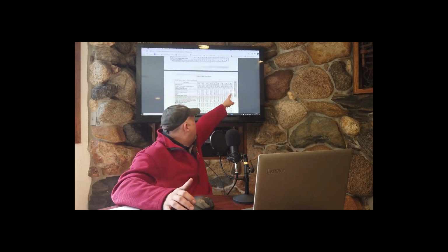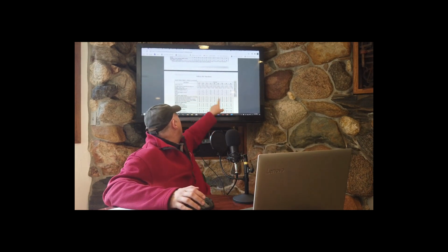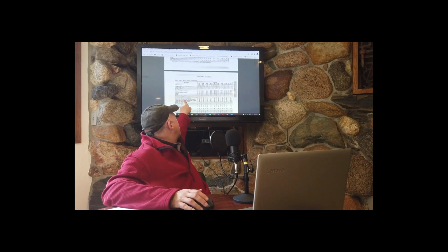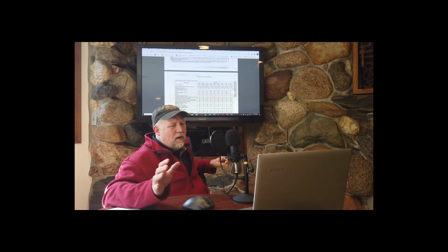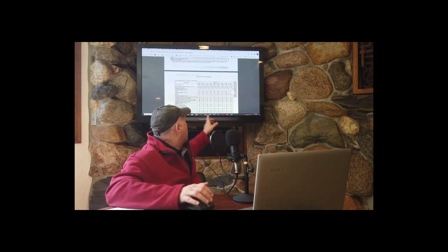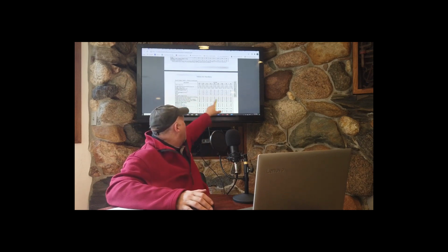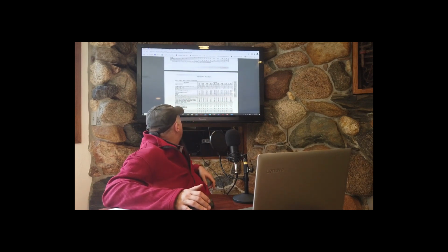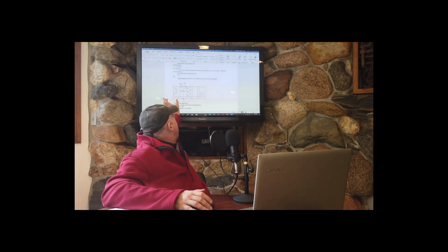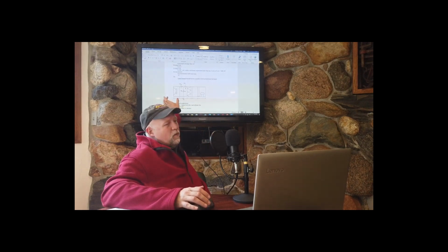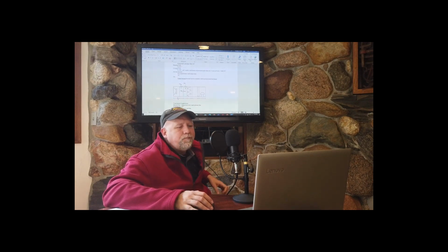So for a 40,000 CFM air handler, if I'm using a belt drive plenum fan, and you don't have to understand why, just trust me that that's what we're going to use. It's that type of fan. That length is 82 inches. So back on our handout here, this first depth length would be 82 inches.